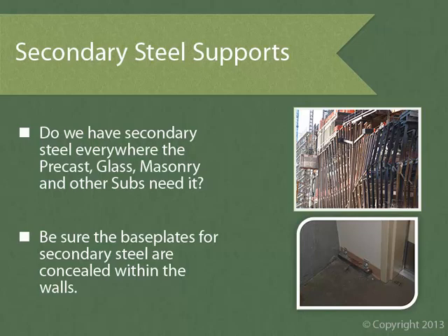In cases such as this, we have two options. We can either use an oblong base plate that is fully concealed within the wall cavity, or we can bury the base plate beneath the top of slab deep enough to cover the top of the anchor bolts. If you choose the latter, be sure to coordinate the thickened slab section with the rebar, formwork, and place and finish subcontractors.